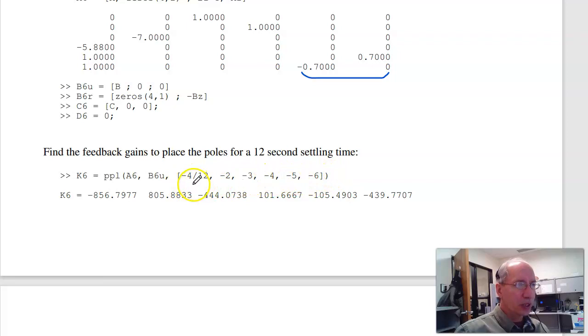Let's make the initial states 0. So that's a zeros matrix, 6 by 1. I've got 6 states. Here's my closed loop A matrix, the B matrix with respect to R, C, and D, time points, 0. My set point is sine of 0.7t. Plot the step response. The pink line is my set point, the blue line is the output. On paper, it should track.